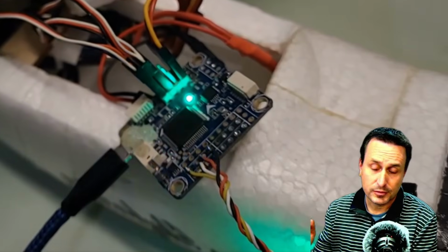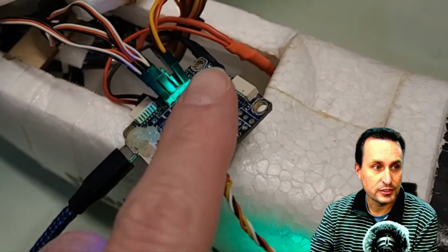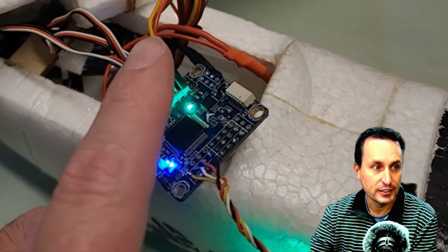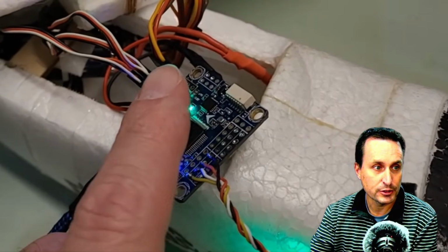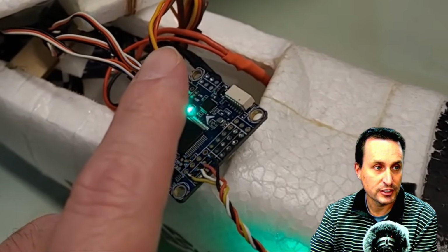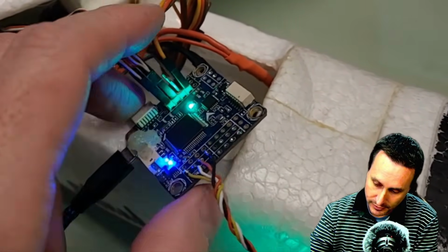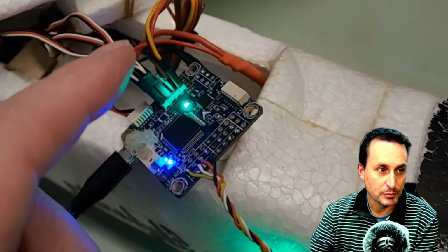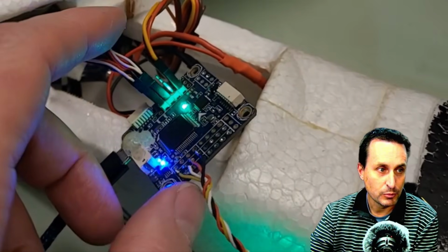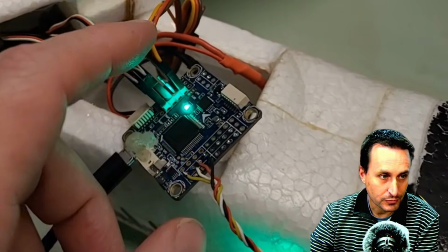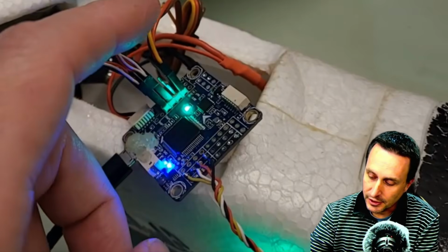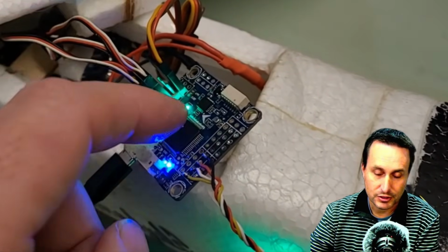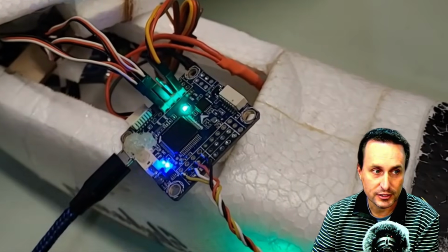Okay, so as discussed, I have these pins all connected. This wire here is coming from the ESC. This is the BEC. This is actually going to power the flight controller. This is going to be the signal. This light brown wire is the signal wire from the flight controller back to tell the motor to spin. But the red wire, or is it red? Yeah, red and dark brown, weird convention, are the power and ground coming from the BEC towards the flight controller to power that and all the servos on that same rail.